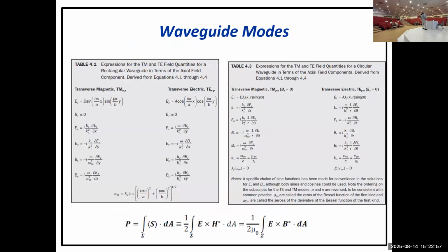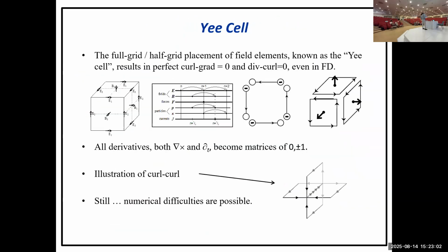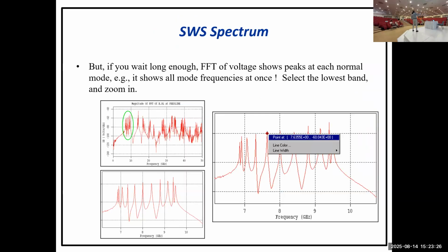Now, when you have software, let me show you. What we do to get the dispersion curve is we have the structure, and then we ping the structure. We send an impulse to see what frequencies will resonate, in time domain or frequency domain, ideally. We see what happens to these frequencies, give it enough time, and you end up with these resonance peaks. This is in computer simulation, if you have a whole structure and you want to get the points.